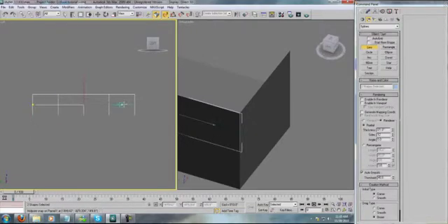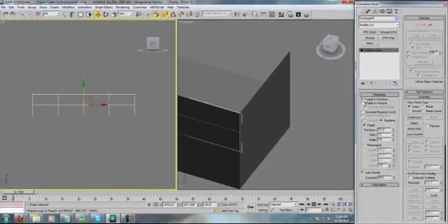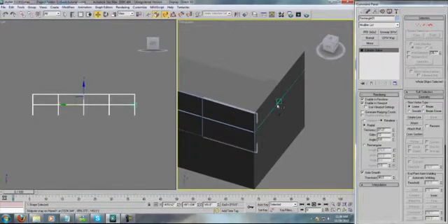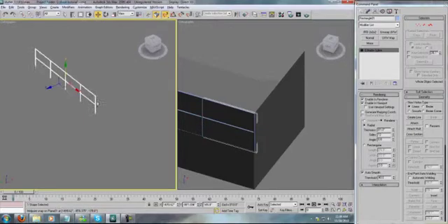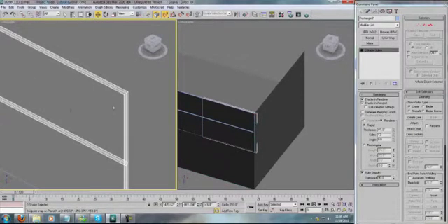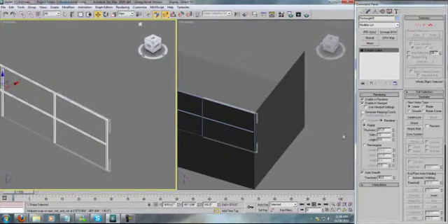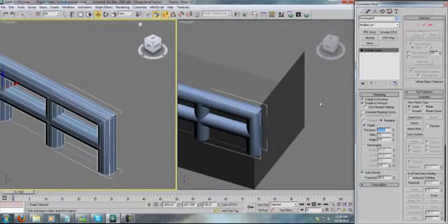And I'm going to make another one that goes over here. Now we've quickly made a spline, and the reason this one is superior to the last one is that I'm going to hit Control Q. That's going to make this one go into poly mode. Let's make this just a foot so we can see it.